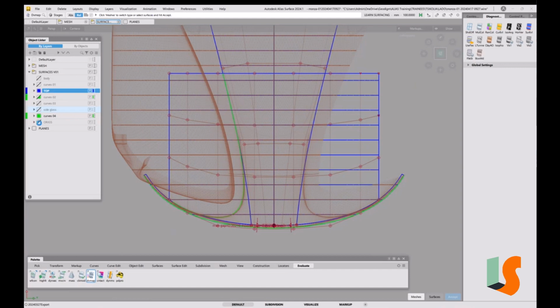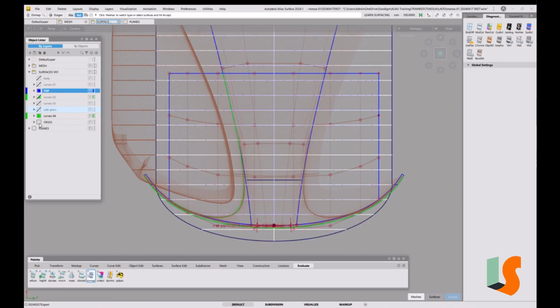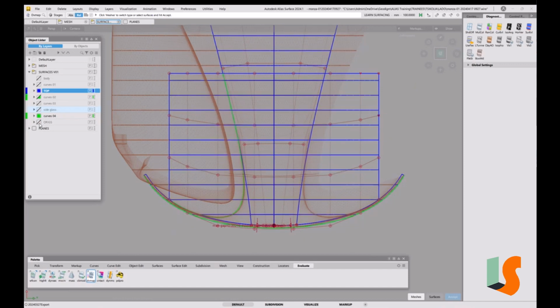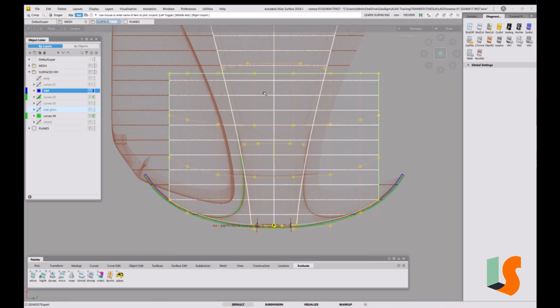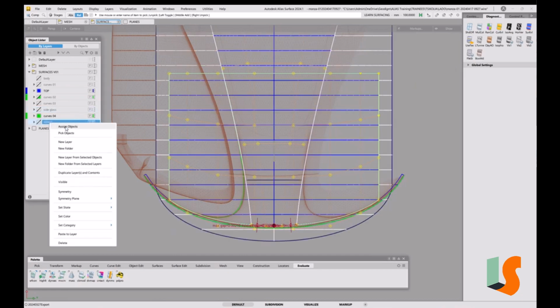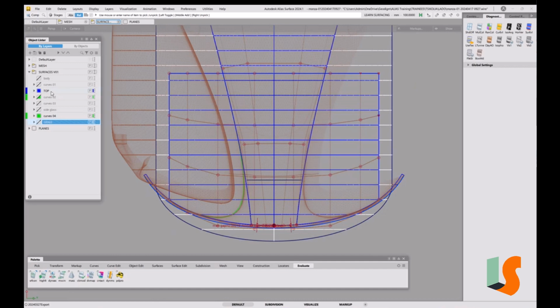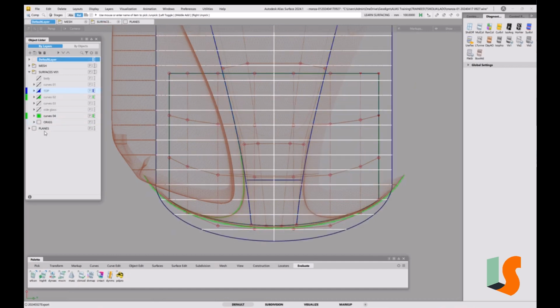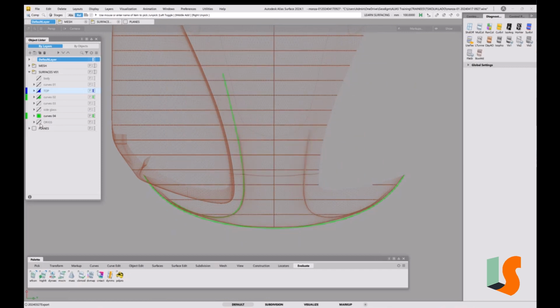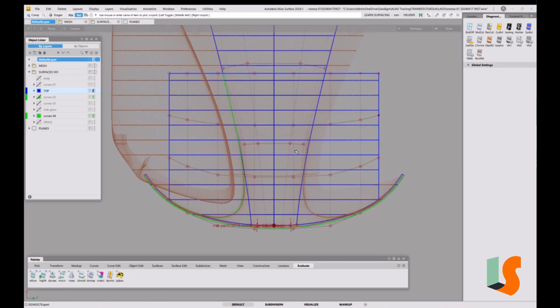Now I've got a layer called Originals, which is where I've got that huge surface that we started at the top of, and I don't want to get rid of this surface, but I do want to trim convert it. But I will keep that as a copy just in case I want to go back. Likewise with this one. So just so I don't lose these, I'm going to copy those, Control C, Control V, and then I'll put those on the original there. Back to top. So we've got those in the background in the original, in case I should need those huge surfaces again, having put quite a bit of work into them.